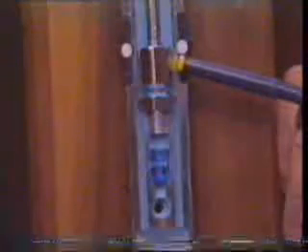As the valve is in the well, tubing pressure flows from the bottom of the valve through these bypass ports and flows all the way up to come in contact with the bellows. This tends to shorten the bellows and tries to take the ball off the seat.